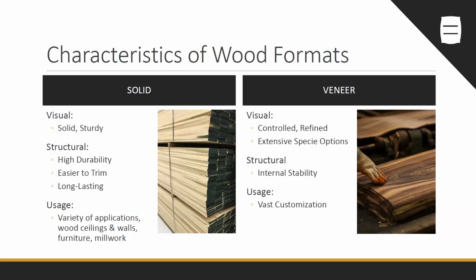Because we have this very thin slice of wood, you are able to ship veneers more economically longer distances. So because of this, you are going to have access to more species if you do specify a veneer. Veneers are internally stable in a climatized area, so they will not shrink or swell, as we spoke hardwood can do. However, there's some cons.